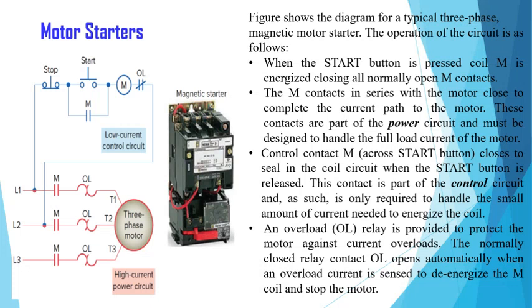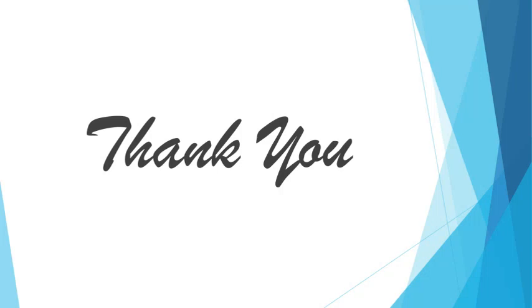Motor starters are available in various standards. When the PLC needs to control a large motor, it must work in conjunction with the starters. The power requirements for the starter coil must be within the power rating of the output module of the PLC. So in today's session, we have identified three different field devices which are used along with the input-output modules of the PLC.